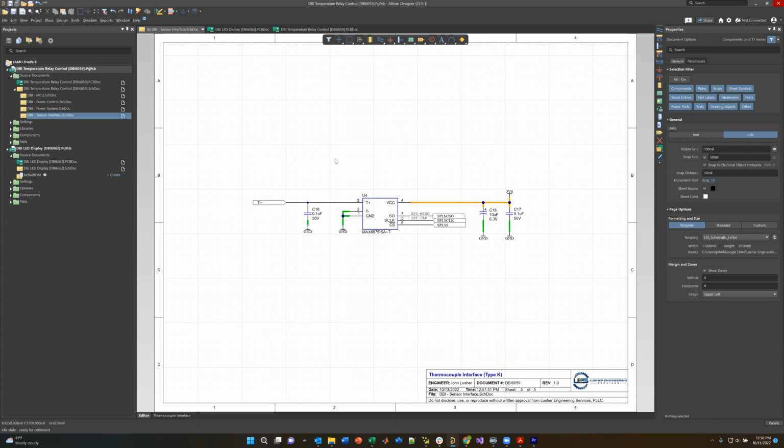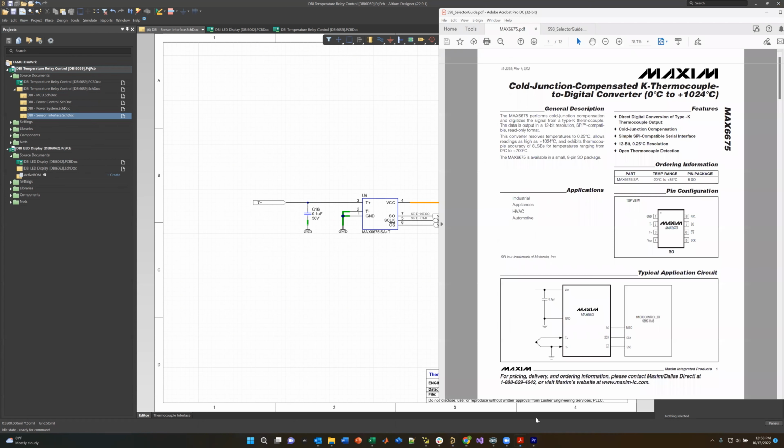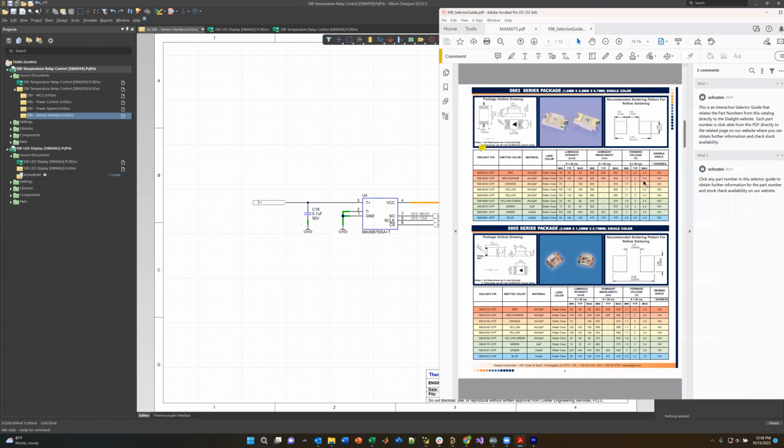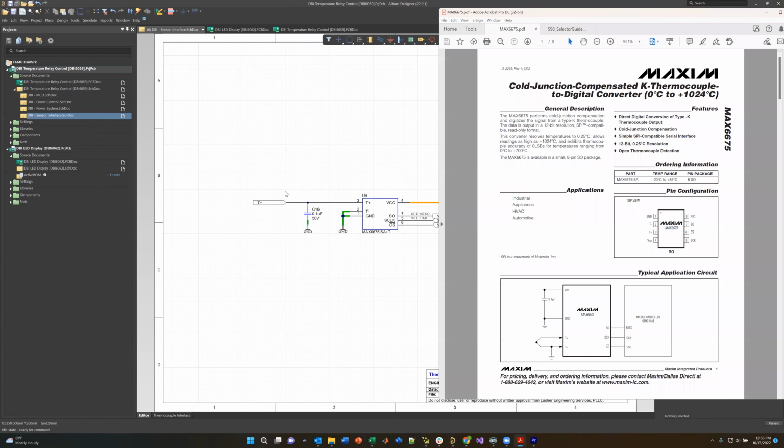So this is all there is to the thermocouple system. This entire sensor comes in, gets read by this chip, and it talks digitally. So this chip does all of the work for us. It is cold junction compensating, meaning it's reading the temperature of this. If you study thermocouples, you'll know what this means. And it's a thermocouple to digital converter, aka analog to digital converter, because this is an analog signal.